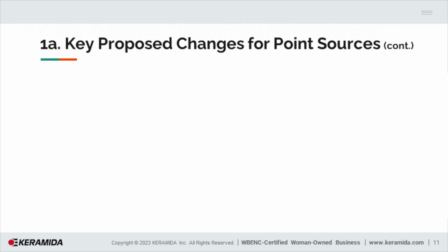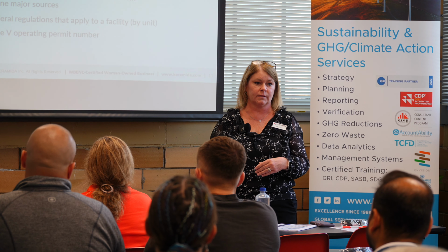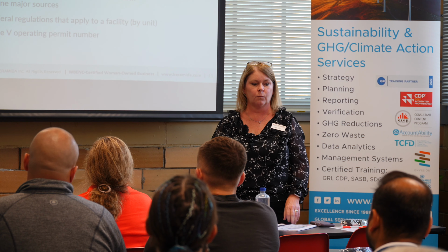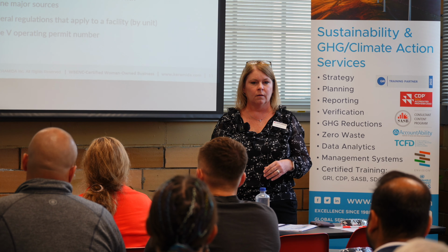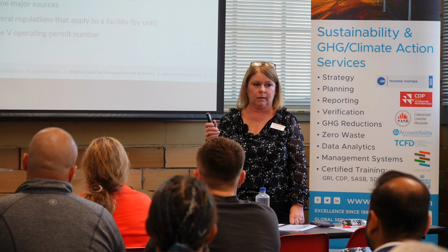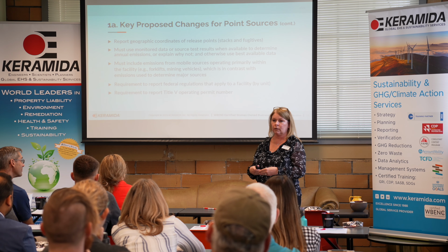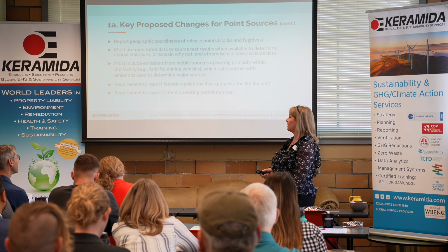Some of the other changes: report the geographic coordinates of the release point. To me, this is a really big deal because you're going to have to report the emissions based on the latitude and longitude of where that emission is actually released. And most companies don't necessarily have that. I know with reporting that we've done and modeling that we've done both in Indiana and in Illinois and other states, the data that is in the state's databases as far as the release points is not very good. There's going to have to be a lot of QA/QC about what are your stack heights, what are your stack velocities, where are they located, and do that kind of mapping of your facility with the GIS lat long.